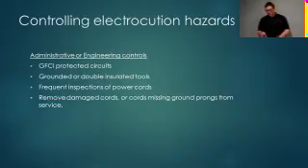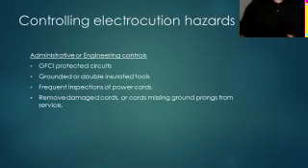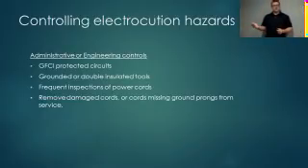One of the biggest things you'll see on a construction site is guys will go around and pull the ground prongs out of their plugs so that they can plug in wherever they want, or so they don't keep tripping the breaker. The reason that ground prong is on there is so that the breaker will trip, or that circuit will be interrupted, and that saves lives.